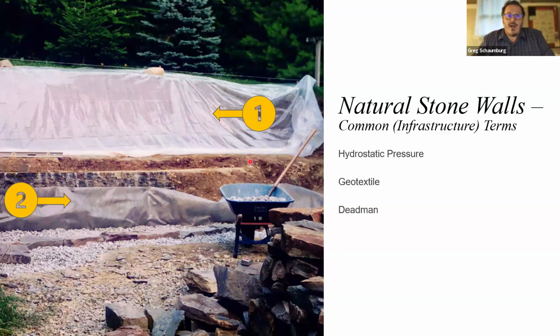So all of the gravel backfill that's in here is an aggregate. We didn't worry about drain tile here because we essentially opted to just do a gravel backfill. So any of the water that pushes through there hits the gravel, finds its path of least resistance, and works its way out to the bottom of the wall. And that relieves what we call the hydrostatic pressure on it.